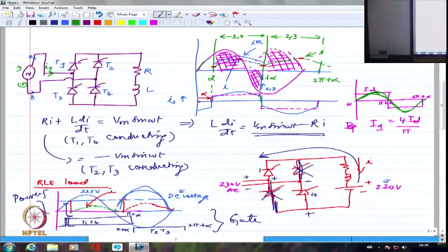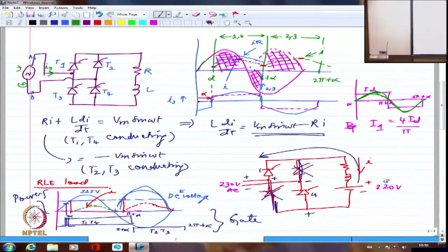So if this is the way the current is being pushed behind, when I calculate the power, generally we say V times I integral over a cycle and average it over the complete cycle. So obviously, wherever the voltage and current are not in phase, I am going to have some reactive power. That's what is manifesting itself as reactive power. So whenever I have a displacement power factor other than unity, I will have a good amount of reactive power content in my circuit. I can't help but have some amount of reactive power content.